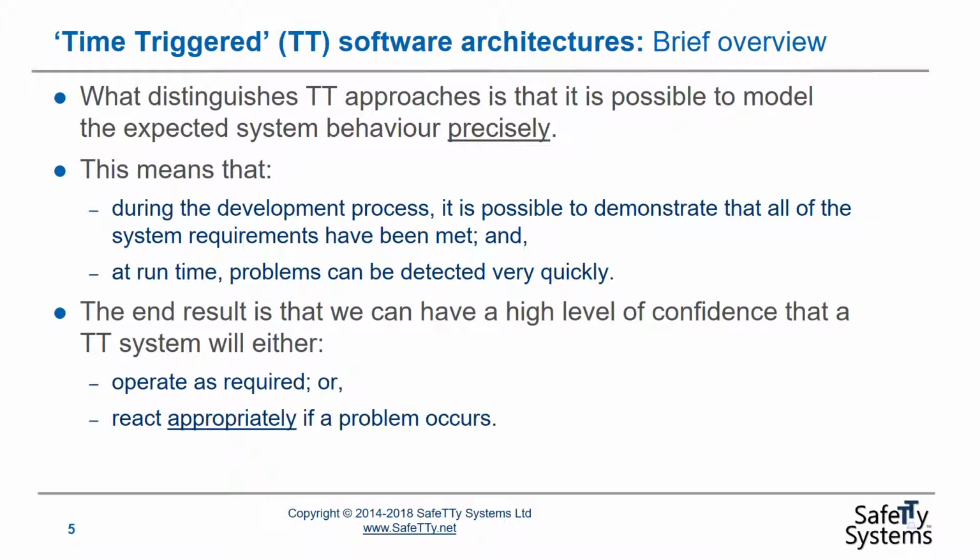So very briefly, what distinguishes time-triggered approaches is that it's possible to model the expected system behavior extremely precisely. This means that during the development process, it's possible to demonstrate that all of the system requirements have been met, and at runtime, we can detect problems in the system extremely quickly. The end result is that we can have a very high level of confidence that a TT system will either operate as required or react appropriately if a problem occurs.